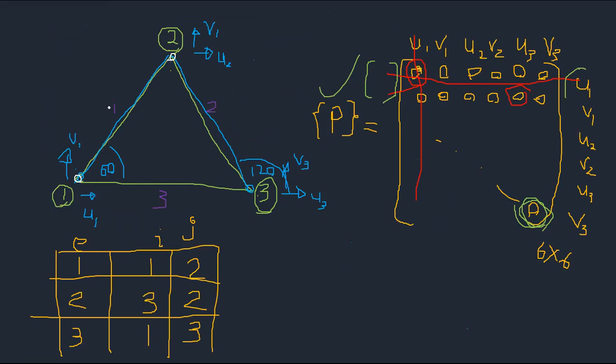For instance, for the first element, you define the first coordinate as the first node, the second coordinate as the second node, because it is creating a 60 degree angle with the positive direction of x, and this is creating a positive direction when it is defined from here to here, right? Third node to second node. If from second node to third node, it's not, right?